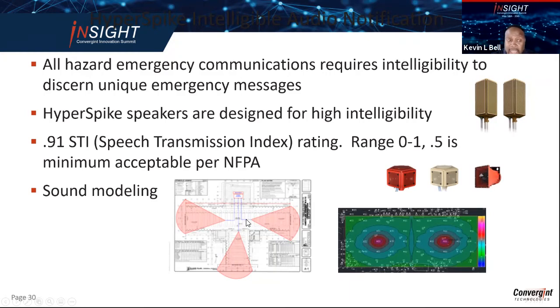We actually took speakers to this environment and tested the omnidirectional and the directional, and we showed the customer that using omnidirectional is too much echoing, which takes away intelligibility. We used directional, and it got through the high ambient noise level without any problem.